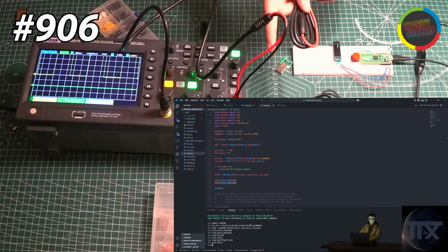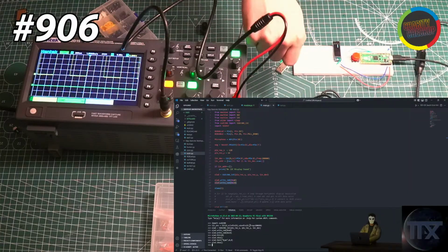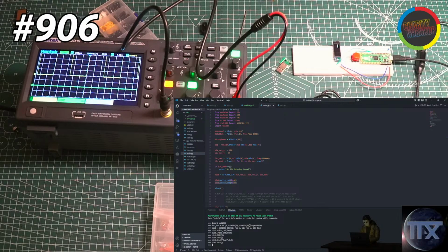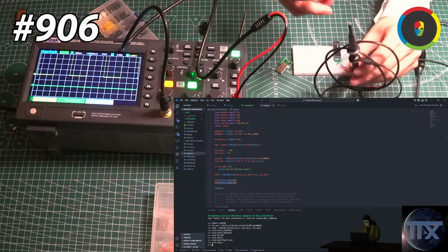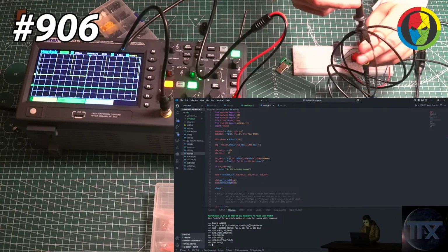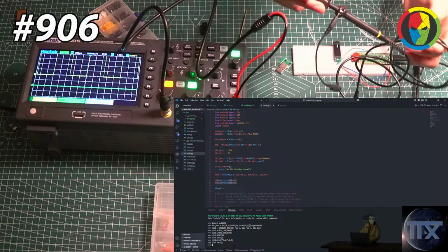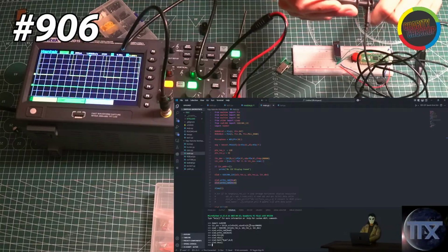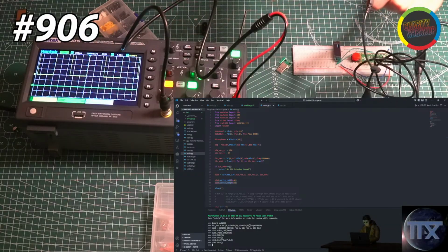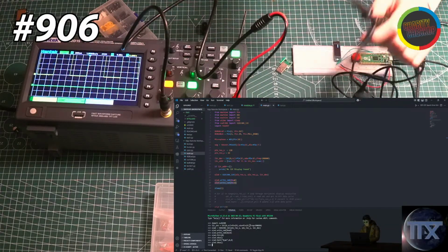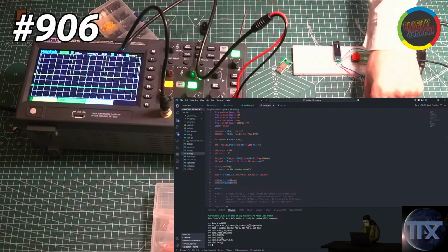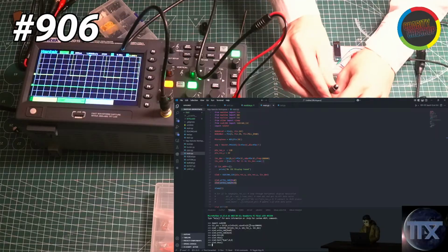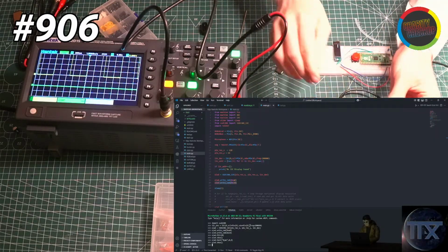Aren't the red and black easier when you just clap onto something? They might be, yeah, but the tip of the probe has a little alligator clip that's pretty nice. If you push down the tip, the whole tip sheath goes, and a little piece of metal pops up, a hook. Yeah, and you can hook it onto things. The ground wire is attached to the middle of the handle there, kind of free floating. That's usually what I use when I do anything, one of those probes.